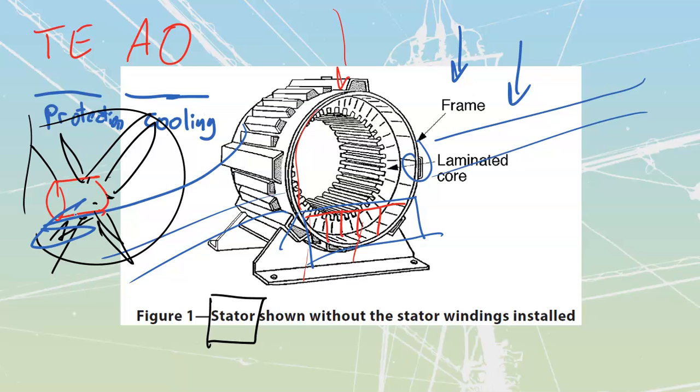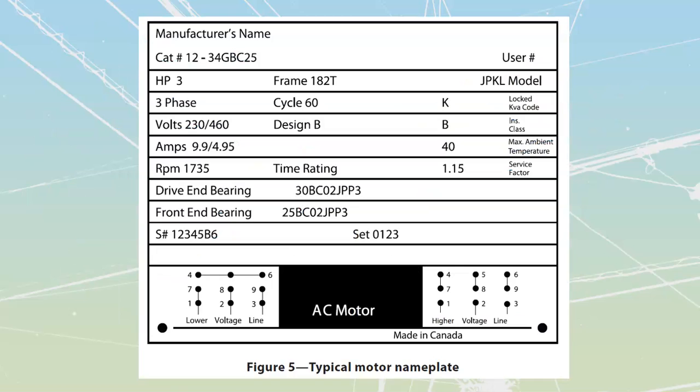Encapsulated or sealed windings are also going to be used sometimes, but they're going to be more expensive. It's where they take the windings and epoxy encapsulate them. They pour material around them that prevents moisture, prevents corrosives, and prevents gases. In some cases, it even gives us explosion-proof types of properties. They're really only a specialized type that you use when you've got heavy, dirty, and dangerous types of industry.